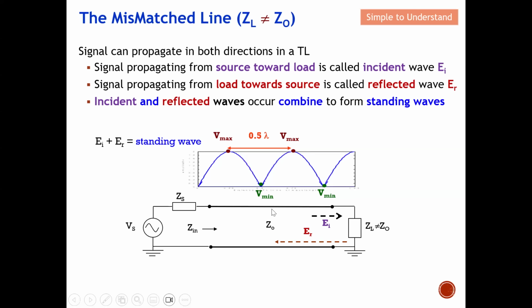So the impedance of the transmission line will not be a constant Z0 anymore, and because the value changes, we have a change in the voltage also. This is basically the standing wave that we describe. We don't talk so much about voltage and current at high frequency, but about the standing wave, which is the voltage standing wave.